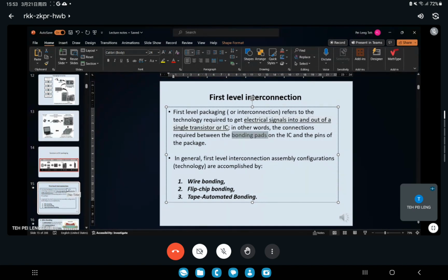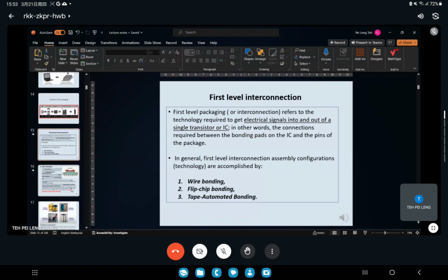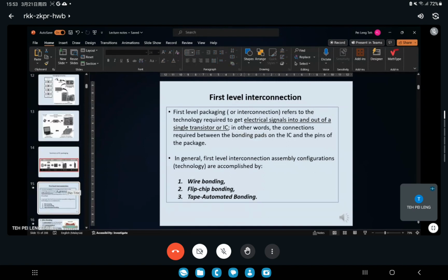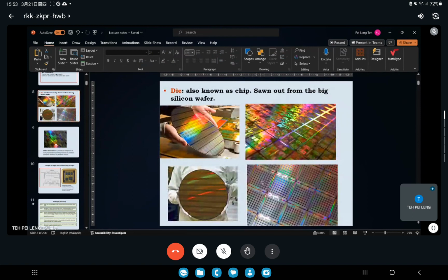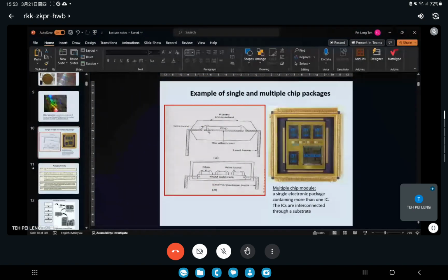Okay, I try to show you a little bit. You see this one is the silicon chip, right? When you want to attach it, you need to saw it, what we call die saw, into single pieces. Then they will pick it using a vacuum and attach it on a chip carrier, forming bonding on this chip carrier.